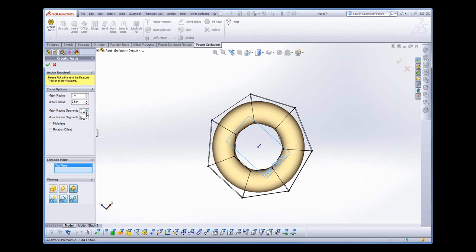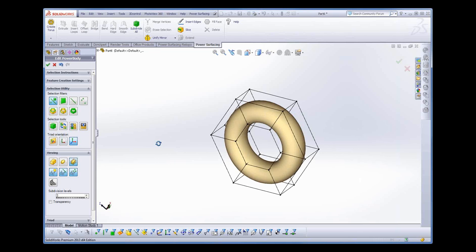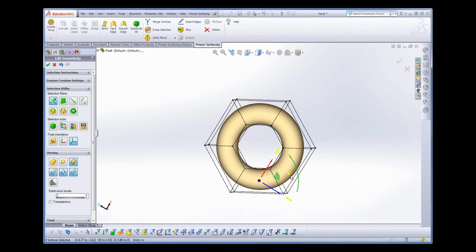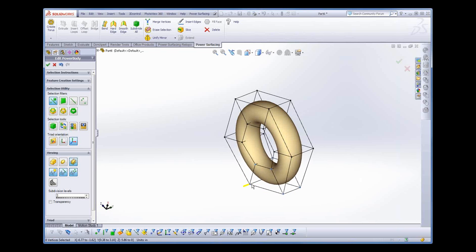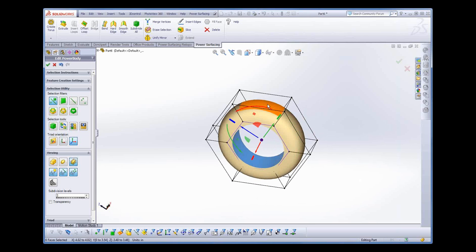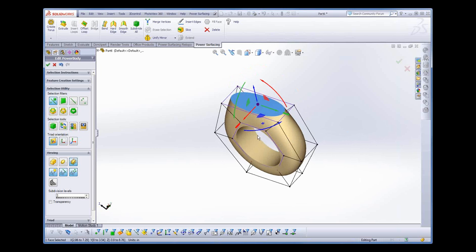There was another question on the question list about importing scan meshes, so I'd like to handle that if you don't mind. Absolutely, go for it. We plan on adding the ability. Right now we can import subD models from any system. Scan meshes, we are in the process of adding through an extension product through Power Surfacing, which will be available pretty soon in a beta release. So look for that. It's pretty good. It will allow you to read in a scanned mesh and create a subD right on top of it, and it will snap down to it. And we'll have a different subdivision called interpolative subdivision, where it will interpolate the points that it goes through instead of kind of shrinking inside it. It's going to be pretty nice.